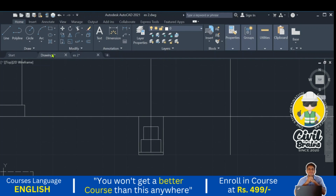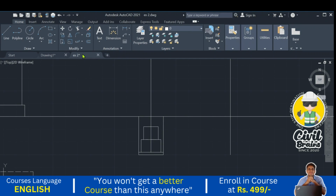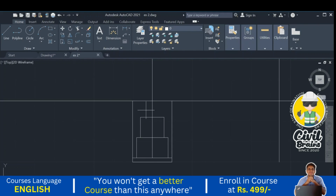Up to the plinth level height we need to take, but what is the width? The width of the plinth we need to take is 0.45 meter. Correct. So, from the right side and from the left side, just go to the offset command, press enter. From the right side, 0.45 divided by 2, that is 0.225. Press enter.